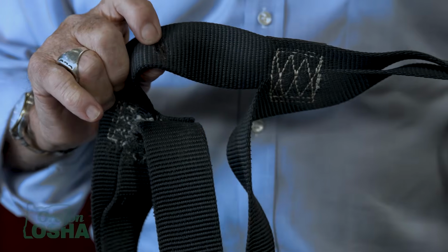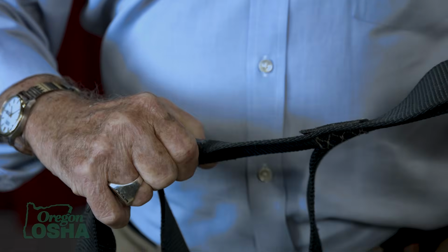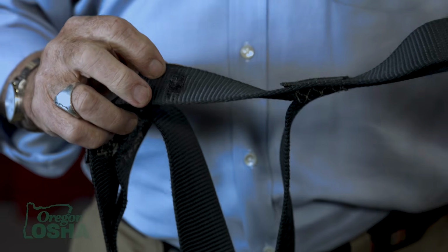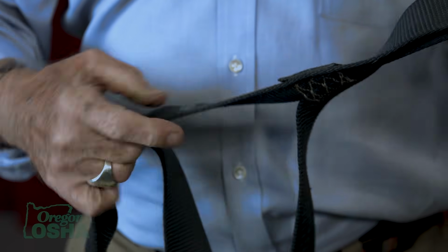This is an area that's subject to a lot of abuse, particularly around heat. We weld something, we brick against it, next thing you know, we've literally welded our harness. Material doesn't function well once it's welded on or gets heat. It melts, it gets brittle, and that's a real problem.